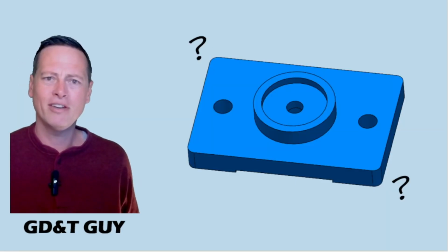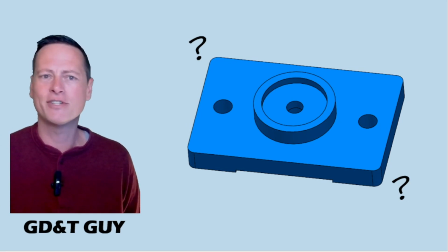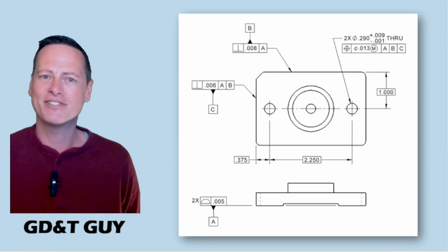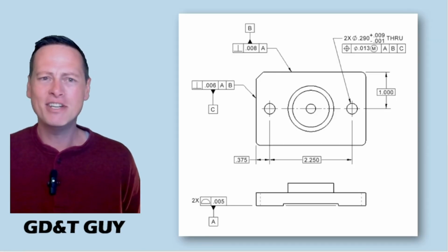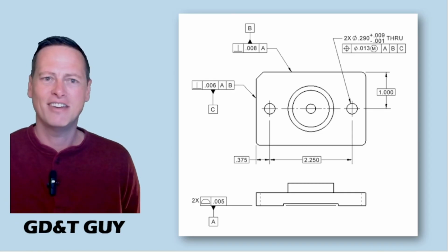And just to prove the point, I can't even tell the difference between one side of this part and the other. I don't even know which corner of this part is that supposedly crucial 000 point, and I don't even care. Then I read in the standard, section 4.8, that I actually need to make this discernible. So I guess one way to do that would be to put a special chamfer up on the upper left corner there. So now we know which edges of a manufactured part are the datum B and the datum C features. It doesn't feel a whole lot less arbitrary though, does it?